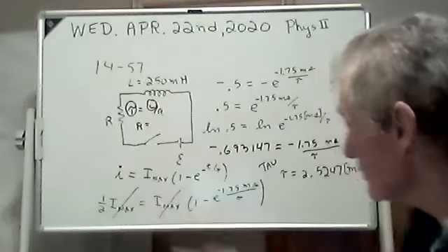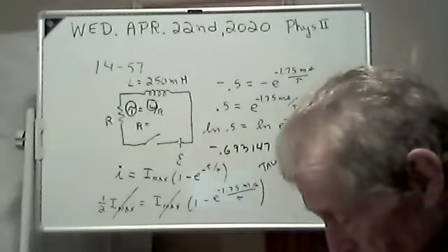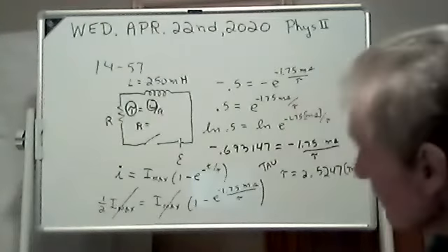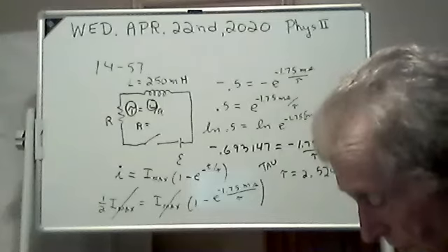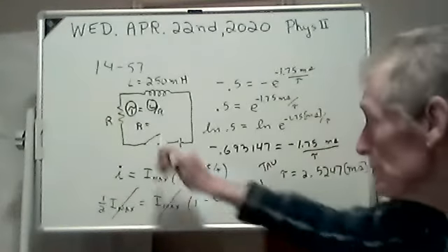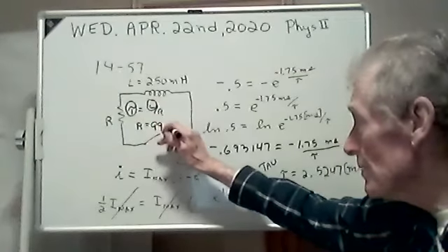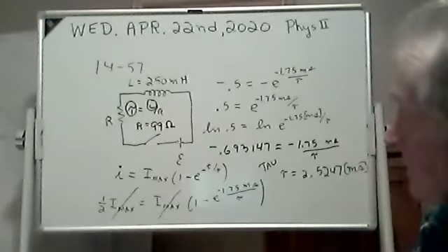I know tau, it's right here. And divide that into L, and here we go. L is 250 e to the minus 3. Boy, Jove, I'm getting 99 ohms. Yay, that's it, 99 ohms.